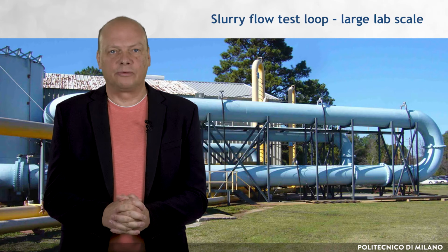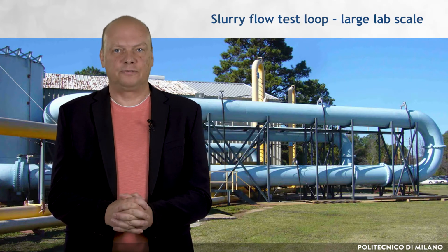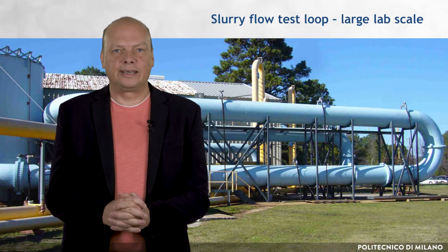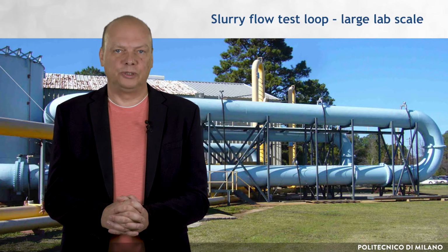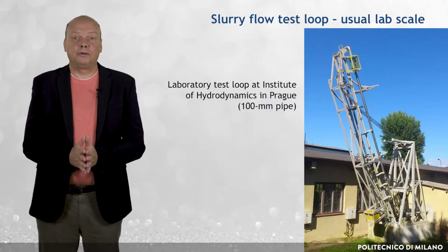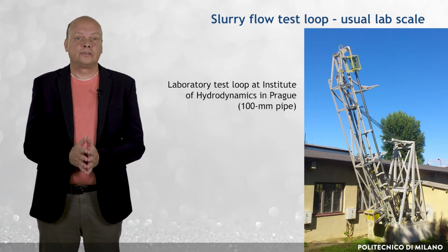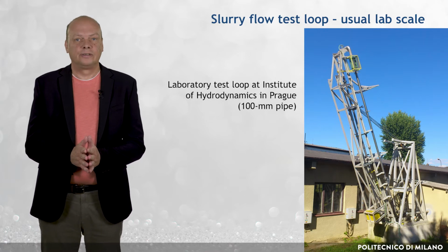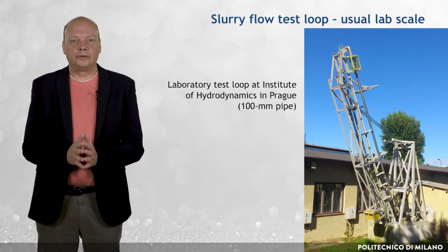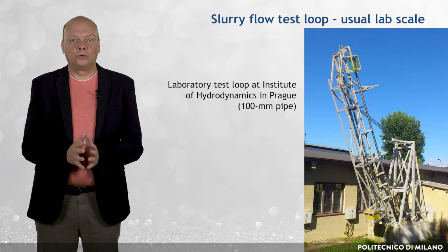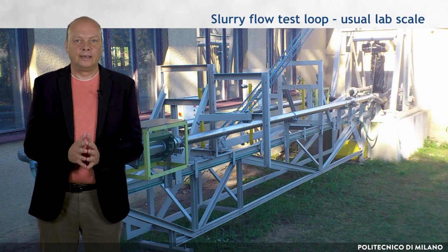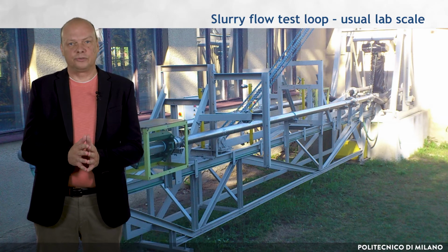Instrumentation is far more restricted for multi-phase flows than their single-phase counterparts, requiring careful placement and analysis if successful results are to be obtained. Testing may be performed in dedicated laboratories or in the field. Both have advantages and disadvantages. Laboratory loops, like the one in the figure, offer controlled, highly instrumented setups where careful measurements can be made but may suffer from scaling issues.